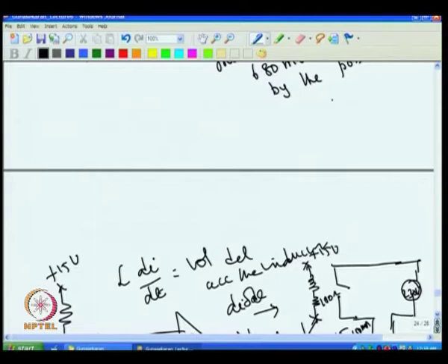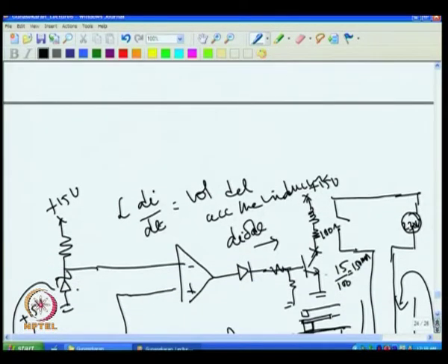That is very high. The voltage at this point tries to rise to a very high value, then the transistor cannot withstand that voltage, and the transistor goes bad. So the lesson is that you should not stop the current flowing through the inductor abruptly, but eventually we have to switch off, only then will the heater go off. To solve this problem, we added this diode.